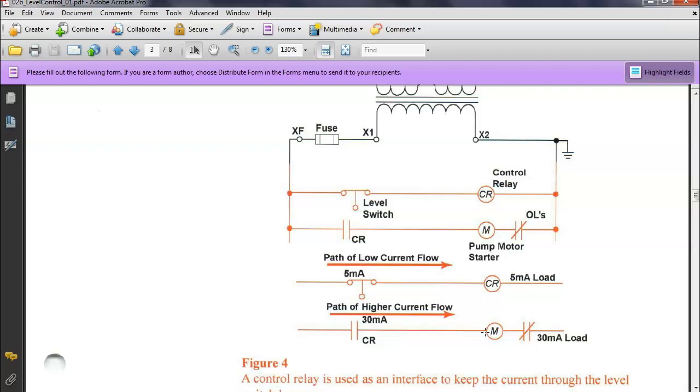And so this would be a charging control. So charging means it comes up and loads up until it does what? Opens the switch, right? A discharging would be a normally open switch, right? And so when your liquid's on, it holds it closed, and then when it drops down, it does what? It opens up. And we combine the charging and the discharging to come up with a what? 2-level. Good.